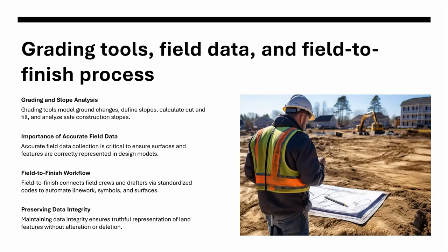Some organizations in Texas, like TxDOT, will have standardized codes. IRF for iron rods found, IRS for iron rods set, PK for nails set in asphalt, MON_TR for tree monuments, FNC for fences, EP for edge of pavement, CL for centerline. These codes mean that when the point file is imported, fences can draw themselves, pavements are delineated, and monuments appear